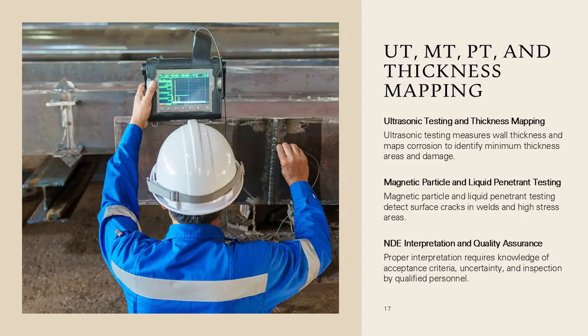Proper interpretation of NDE results requires an understanding of acceptance criteria, measurement uncertainty, and code requirements. Inspectors must ensure that NDE is performed by qualified personnel and that results are accurately recorded and evaluated in the context of overall vessel integrity.